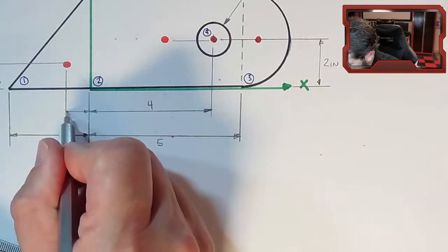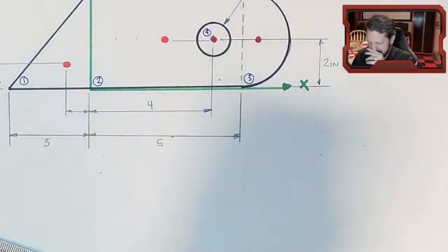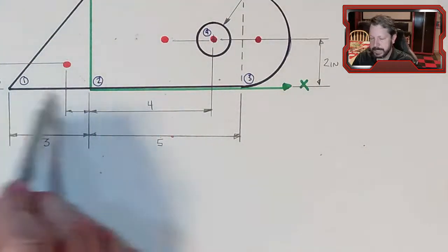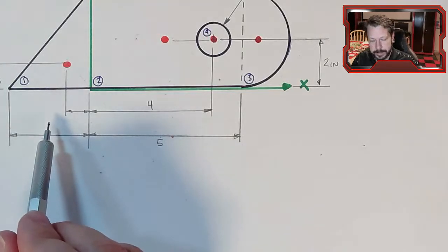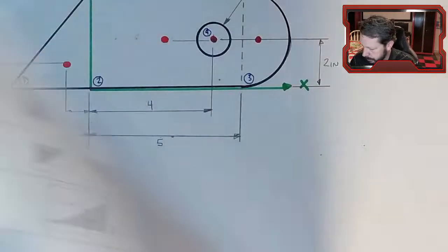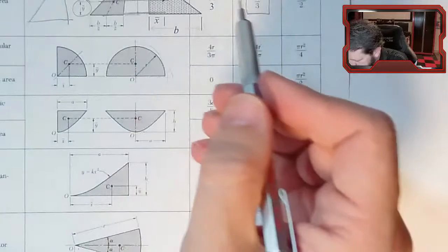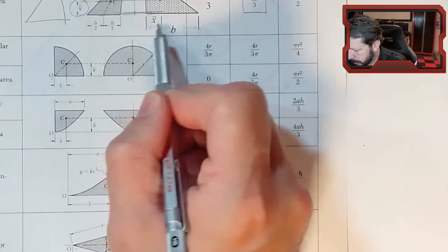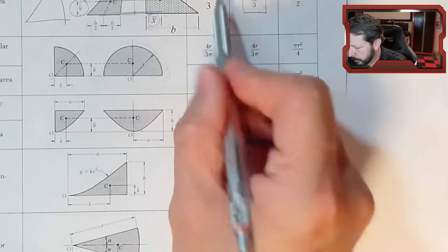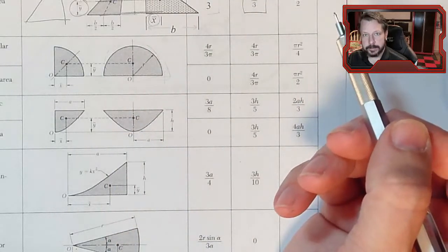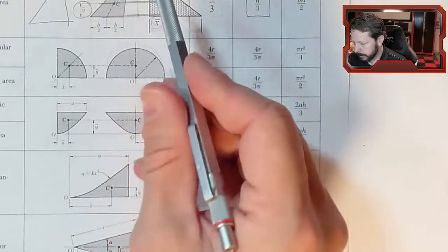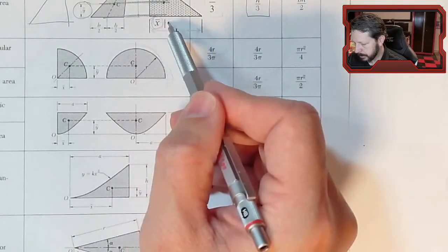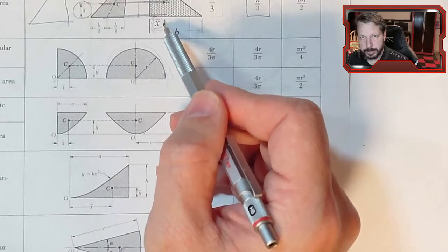So if you draw this and you've drawn things more or less to scale, then that distance does not look like 2/3 of the base, right? So you have to go back and say, well, why is that? And then you check your chart over here, and here they've got an x bar labeled as 1/3 of the base. So what's going on? You have to match up the shape that you have and where these dimensions are being measured from and to.